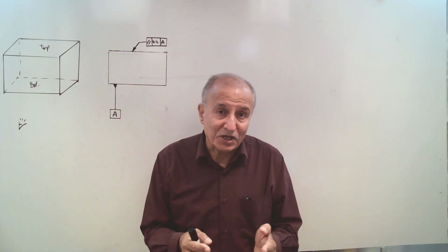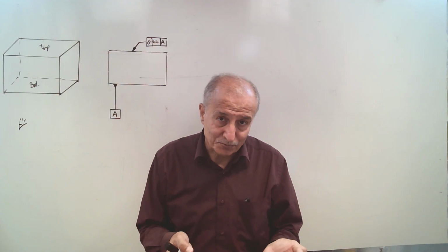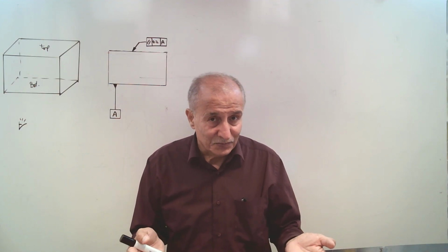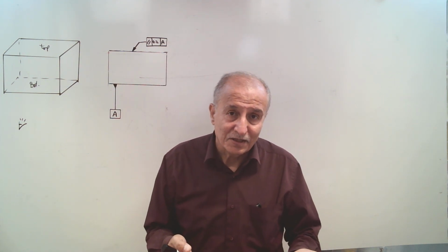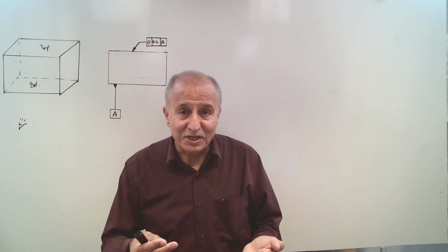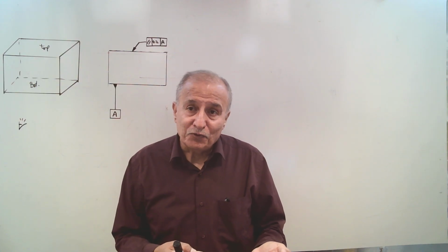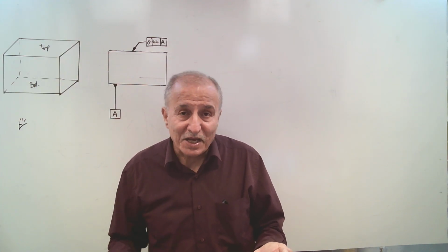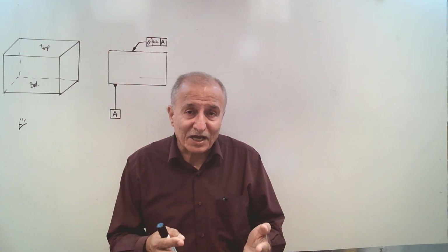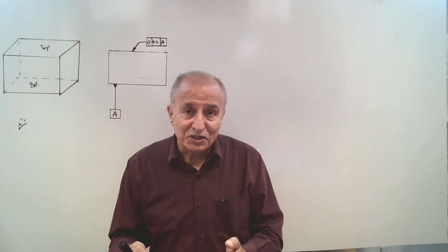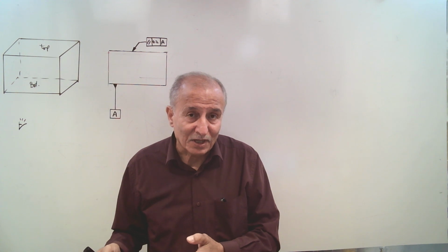And because position indirectly controls orientation, this tolerance for orientation is normally smaller than the tolerance for position. But refinement doesn't mean only that it must be smaller. Refinement means that if you specify position and also parallelism, you emphasize the parallelism of this surface, not only its location, but also its parallelism to datum A.